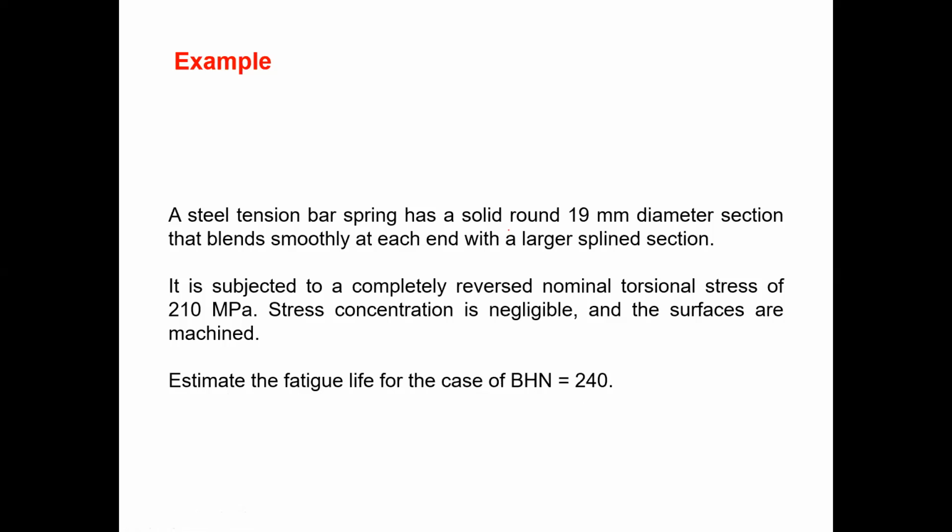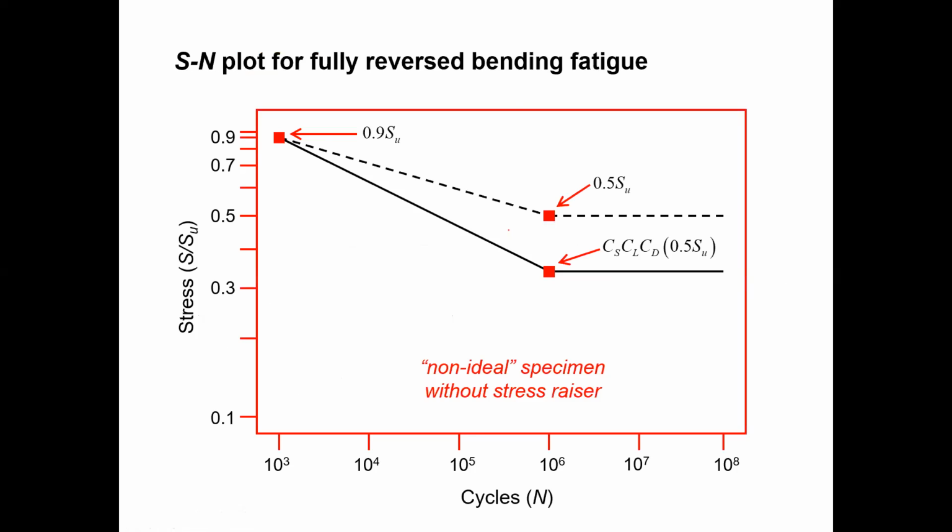In the previous slide, here, CS, CL, CD, is it equal to shear force? S means shear force? You mean the whole equation? No, this is not a shear force. This is actually the 10 to the power 6 cycle fatigue strength.